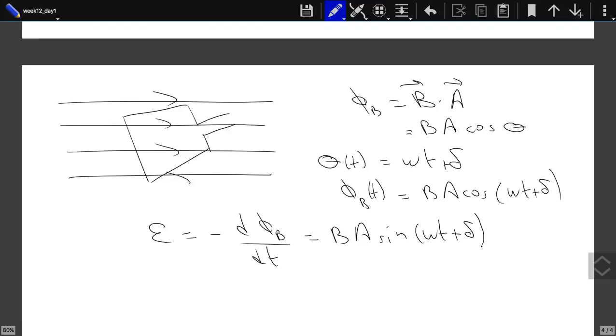When it is aligned with the magnetic field, there won't be any torque. But if this is a massive object, it will have inertia, so it will keep rotating. Then the dipole will again feel a torque, trying to align it in the direction of the magnetic field. So if you don't change the direction of the current, it will not be rotating. It will just be oscillating.